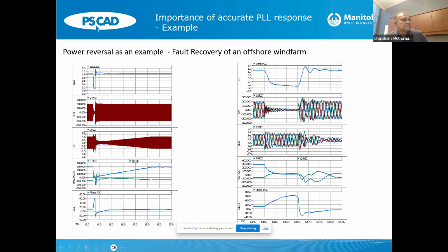I think there's concern that this might impact existing protection, reverse power flow, whatnot. So the designers, the equipment vendors are challenged to avoid these type of little things. And this really is because once you clear the fault, your phase angle at the bus obviously would shift, and it takes a while for the PLL to lock. You can't avoid that. You can minimize these type of things, but you can't avoid that. But to do this type of detailed analysis, you really would need to have EMT type simulations.